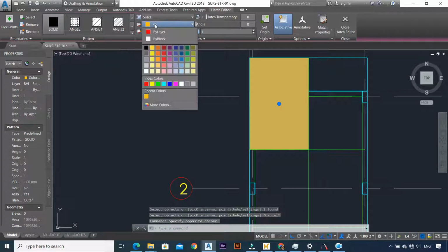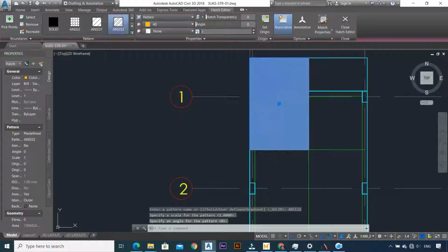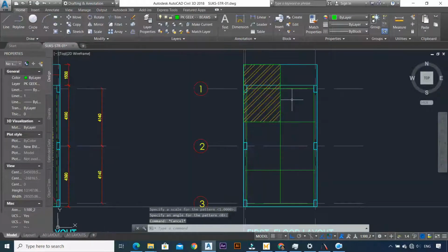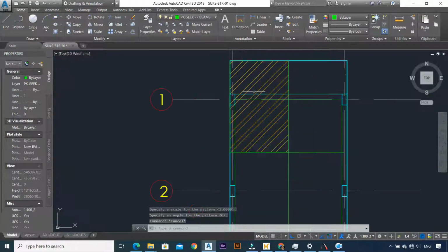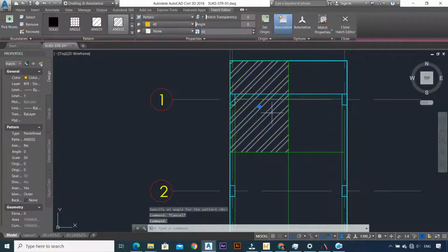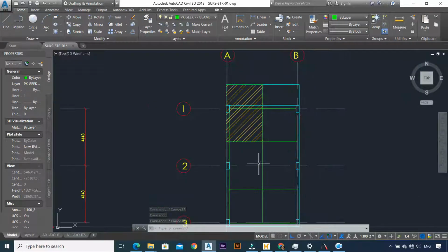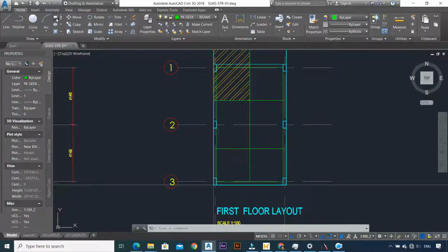And then we're going to say it's 40, then we're going to change it to inside 32, then we're going to change this to 50, the scale. So effectively, what I have done by doing this is I have established the tributary area, or to say this is the area that is going to be distributing all of its loads to this specific column. And watch as I do the next.